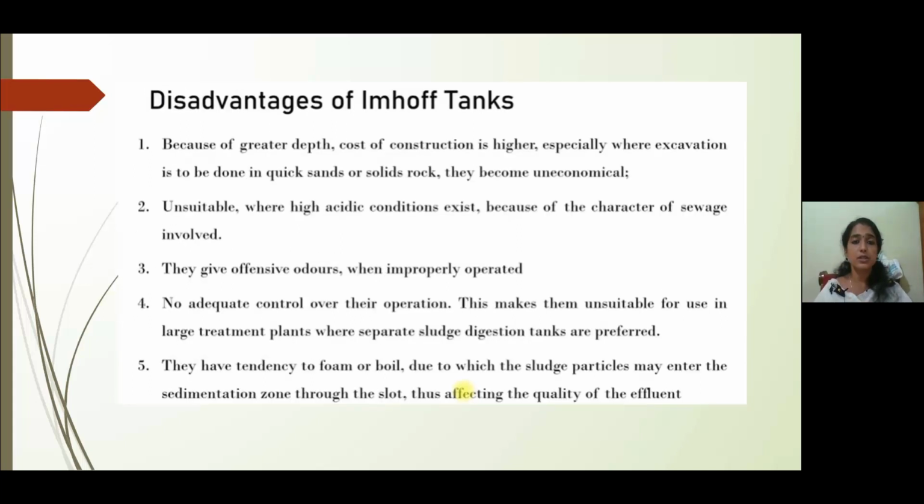Then the disadvantages of Imhoff tanks: because of the greater depth, the cost of construction is higher, and especially where excavation is to be done in quicksand or solid rock, they become uneconomical. Unsuitable where highly acidic conditions exist because of the character of the sewage involved. They give offensive odors when improperly operated.